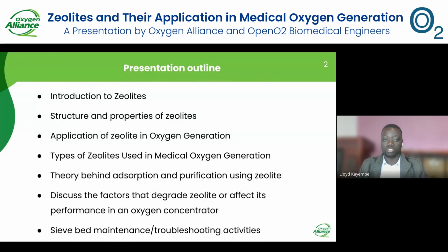Then we also discuss the science behind the adsorption process and purification using zeolite in relation to the pressure swing adsorption process. We also discuss the factors that degrade zeolite or affect its performance in the long run in an oxygen concentrator. Then lastly, we are going to discuss the maintenance activities done around the sieve bed that contains the zeolite in the portable oxygen concentrator.